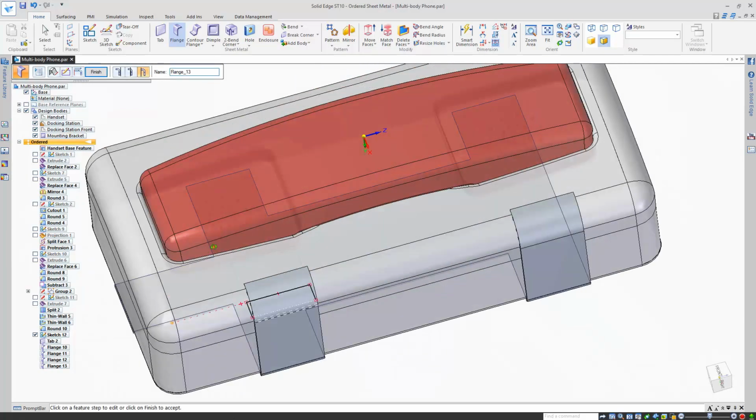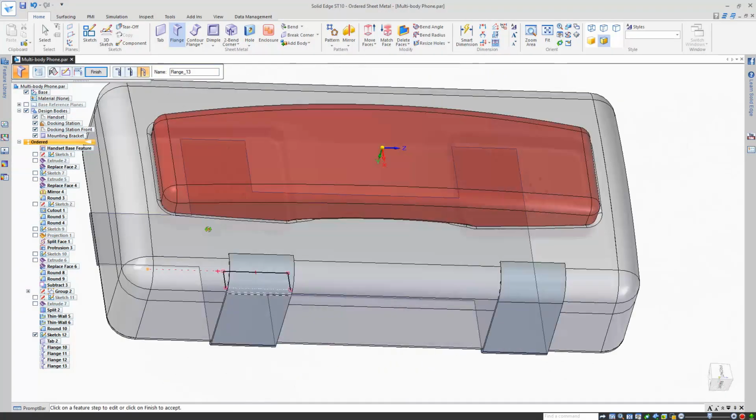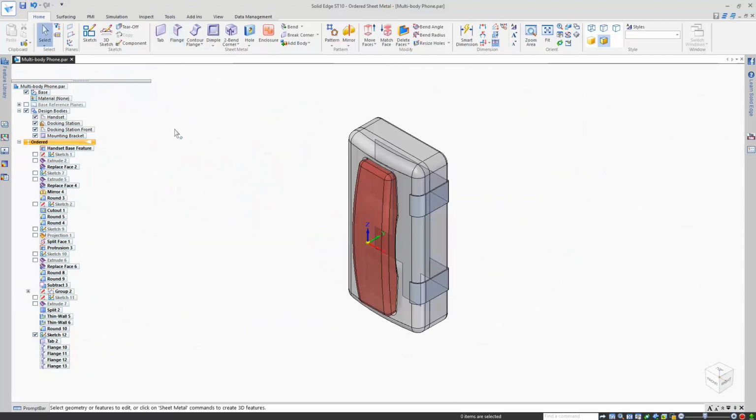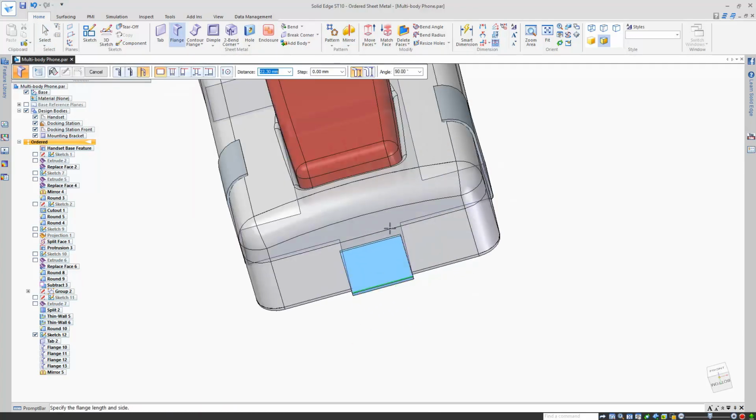Now that's half the flanges done, and I'll take this opportunity to remind everyone of the golden rule of CAD. If possible, reuse your work. In this case, with the mirror command, I can reflect all 4 flanges about the ZY plane. One more flange at the bottom shall finish the bracket.